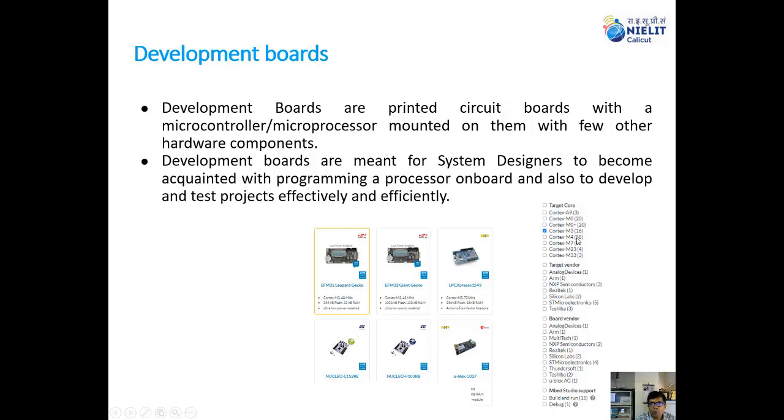And what are development boards? Generally, in embedded scenarios, when you want to develop something or implement a concept, people will initially implement things or develop the prototype on a development board. A development board is a PCB with the main microcontroller, and additional peripherals like connectors are terminated there, plus a few passive components, drivers, etc. on the board.